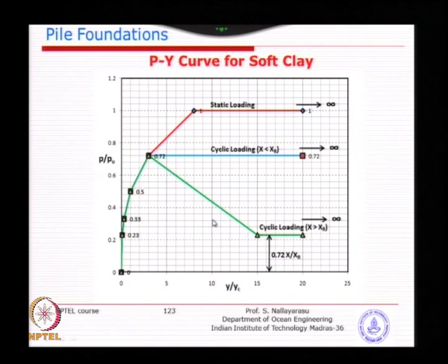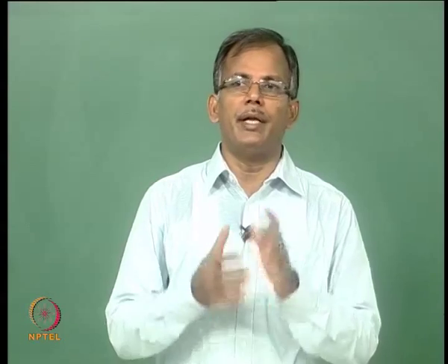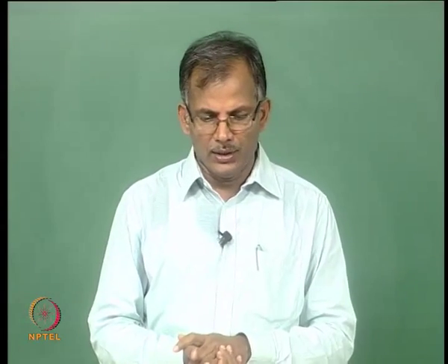So, that is the idea that the top few meters of soil, the initial assumption by Brinch Hansen and others of 1.5 diameter, I do not want to take any strength at all. So, completely ignored, whereas here you could still consider, but the effect is going to be quite less. So, that initial work actually reflects the assumption that the first few meters will not be able to contribute any resistance towards the lateral capacity.